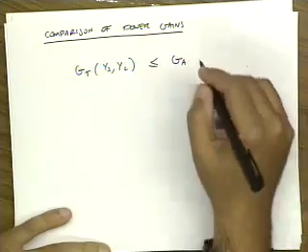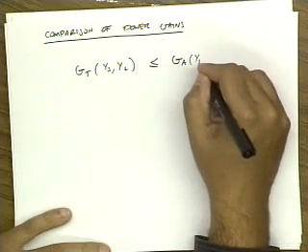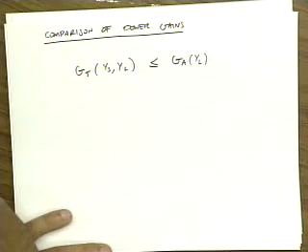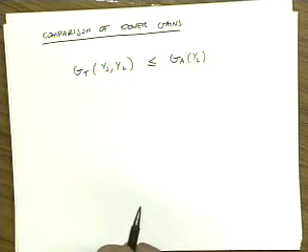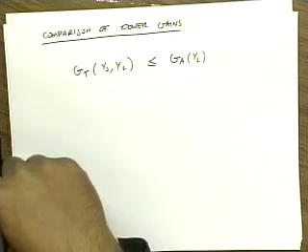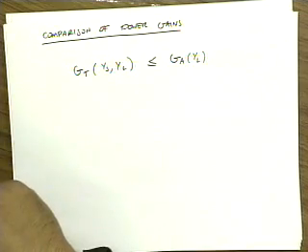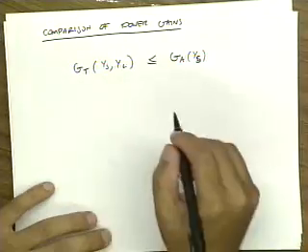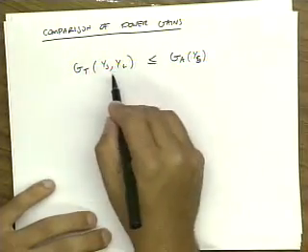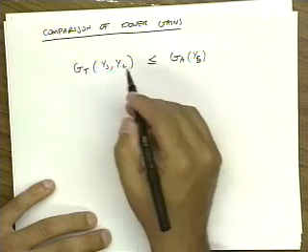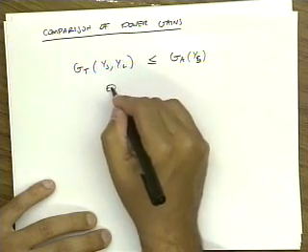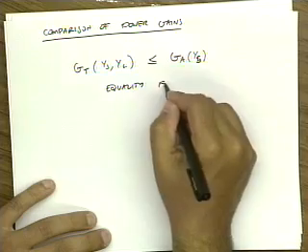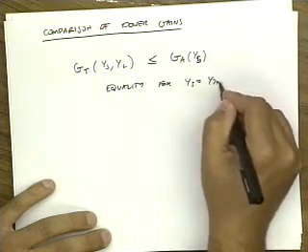And the available gain is only a function of Ys. Let me just double check: available gain is power available from the two-port divided by power available from the source, so it should only be a function of Ys. And we found that equality only happens for Ys equal to Yin conjugate.